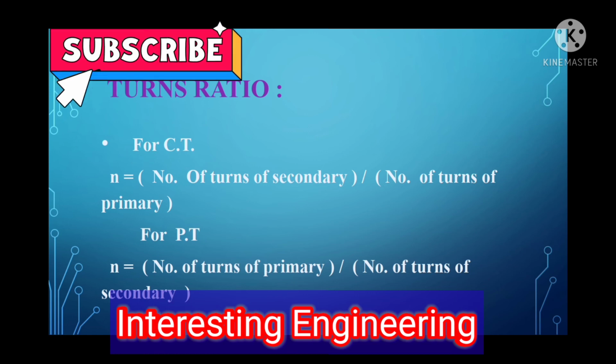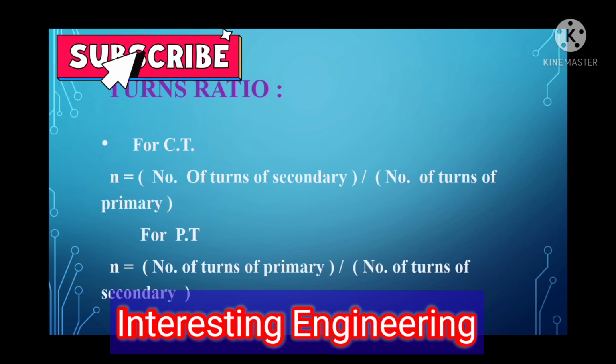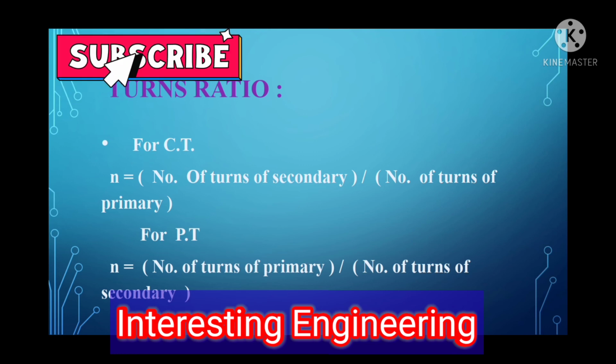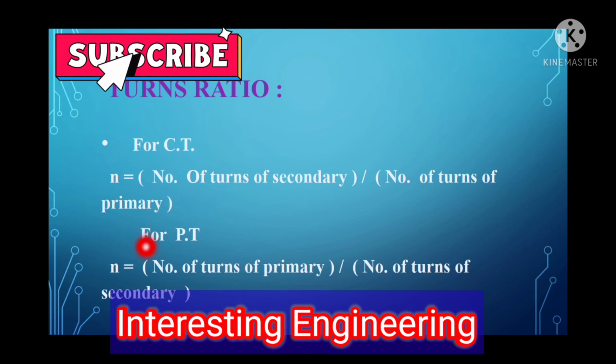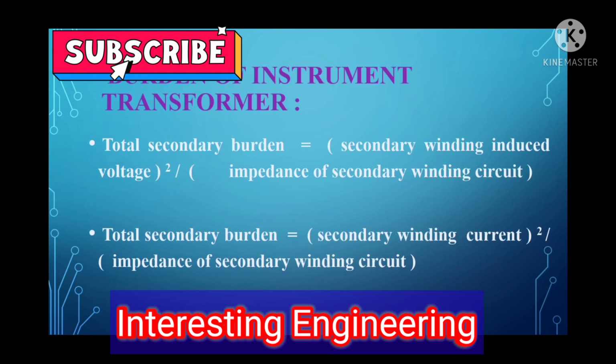You should remember that in the case of current transformer there's only a single turn in the primary winding, whereas in the case of potential transformer there will be many turns in the primary winding. So based on that only the turns ratio differs in both cases. So n is equal to number of turns of secondary by number of turns of primary, whereas for potential transformer it is number of turns of primary by number of turns of secondary.